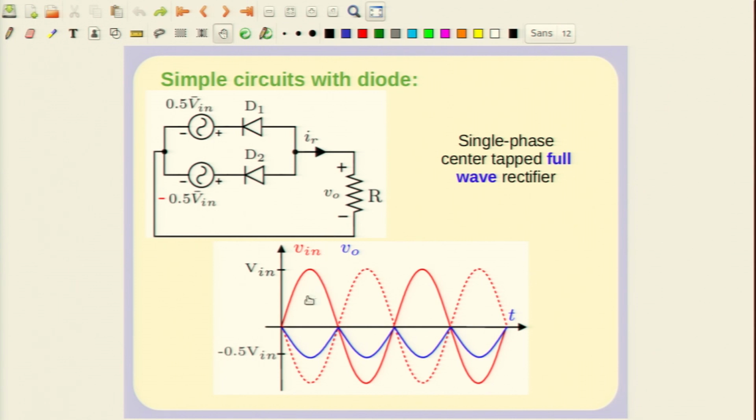That voltage is in fact negative. So, you will get a negative voltage here, and the current IR will also have the same waveform, and also will be negative, with IR shown with the reference direction in the way it is shown. The current will in fact be negative and will follow the voltage waveform.